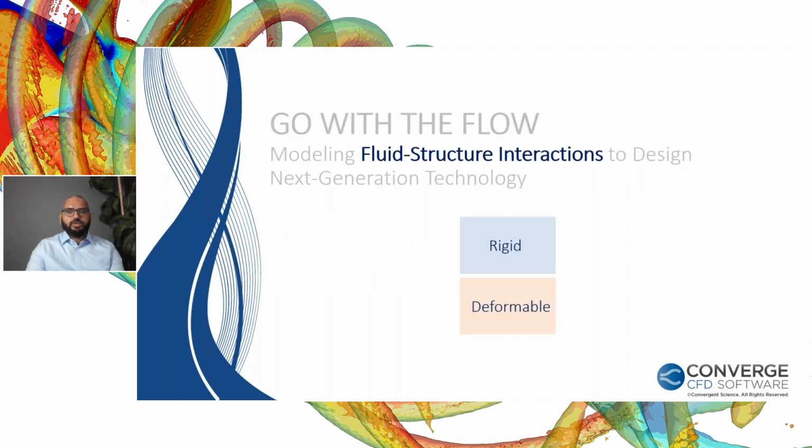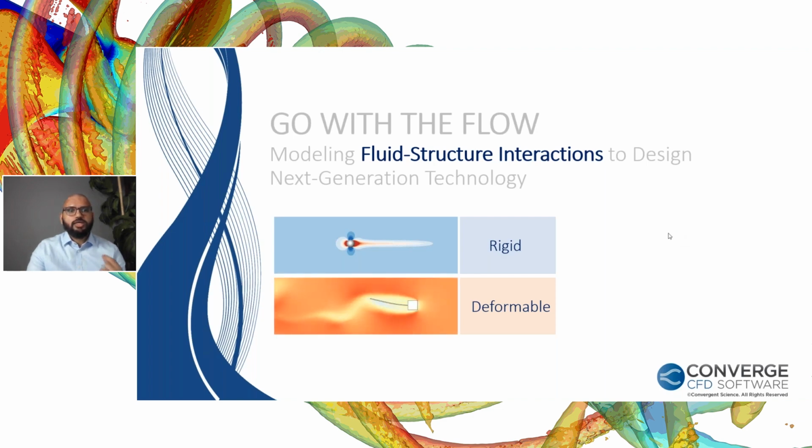So for those who are not familiar with the term, FSI, or fluid structure interaction, refers to cases where there is an interaction of some movable or deformable structure with an internal or surrounding fluid flow. The solid could be a rigid body, in which case it undergoes a rotational and translational motion due to the fluid forces acting on it, or it could be a deformable body, in which case the solid deforms depending on the pressure and the fluid stresses acting on the boundary.